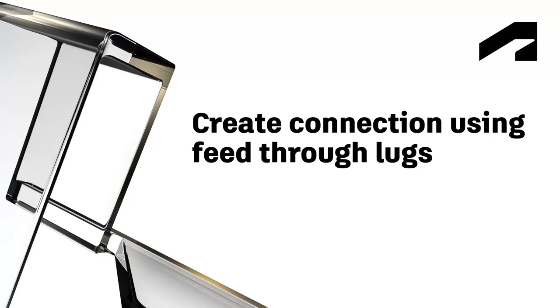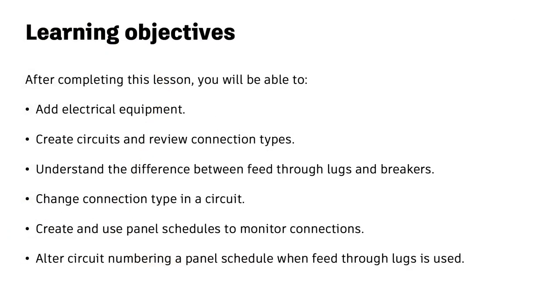In this video, you will add electrical equipment, create circuits and review connection types, understand the difference between feed-through lugs and breakers, change connection type in a circuit, create and use panel schedules to monitor connections, and alter circuit numbering in a panel schedule when feed-through lugs is used.